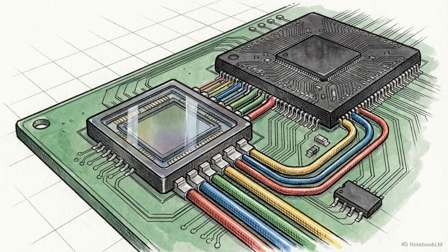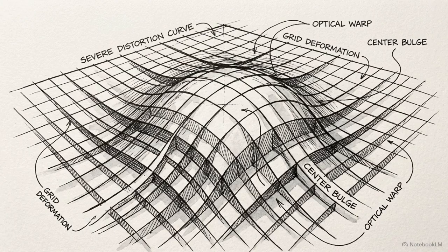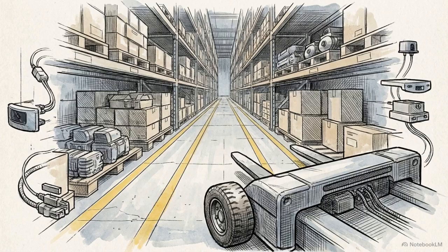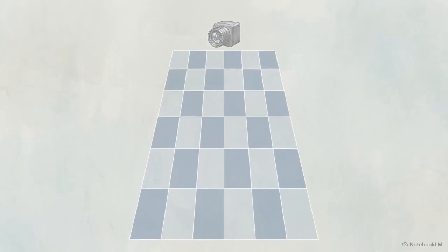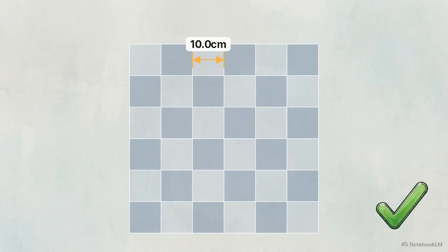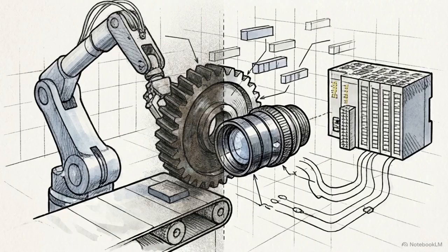Once the physical light hits the sensor, the frame grabber and embedded camera pipelines initiate the transition from physical space into digital space. This introduces the challenge of geometric distortion. When cameras are mounted to moving robots or autonomous vehicles to observe large scenes, the perspective is inherently skewed. This diagram demonstrates inverse perspective mapping. By correcting the visual angles, skewed data mathematically morphs into a perfectly flat, top-down, two-dimensional plane, enabling the consistent measurement of planar features.